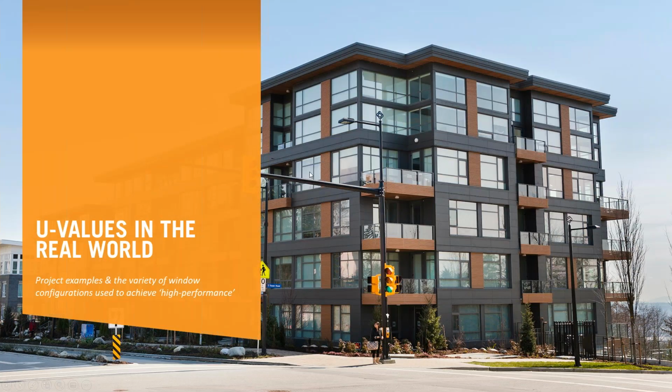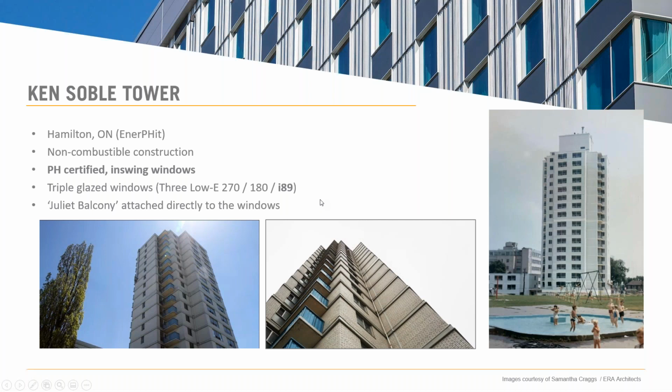Okay, a few project examples. The last few minutes here, we're going to go through and give you some visuals on how high performance windows are applied. This is a project in Hamilton, Ontario. It's a Passive House certified Enerfit retrofit project. Very, very interesting project. There's a lot of case studies on this that you can see. Cool thing that they had to do to this project to achieve their goals was cut off all of these balconies that were massive thermal bridges. So you can imagine all of the structure exposed here is just leaking heat like crazy.